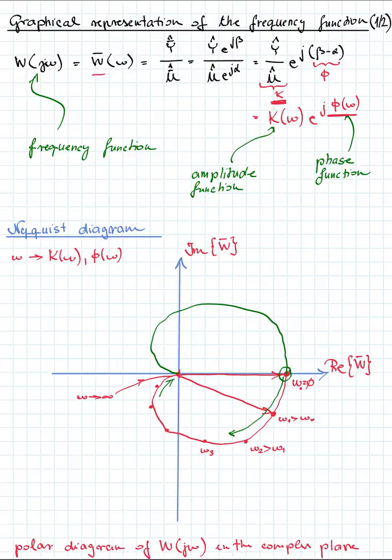But sometimes, especially for the stability analysis, please remember that we are going to come back to Nyquist diagram as stability analysis, and sometimes at the design of PID type controllers. And in that case, we need the complete Nyquist diagram. Complete means that our omega is running between minus infinity to plus infinity, but of course physical meaning has only for positive omega.